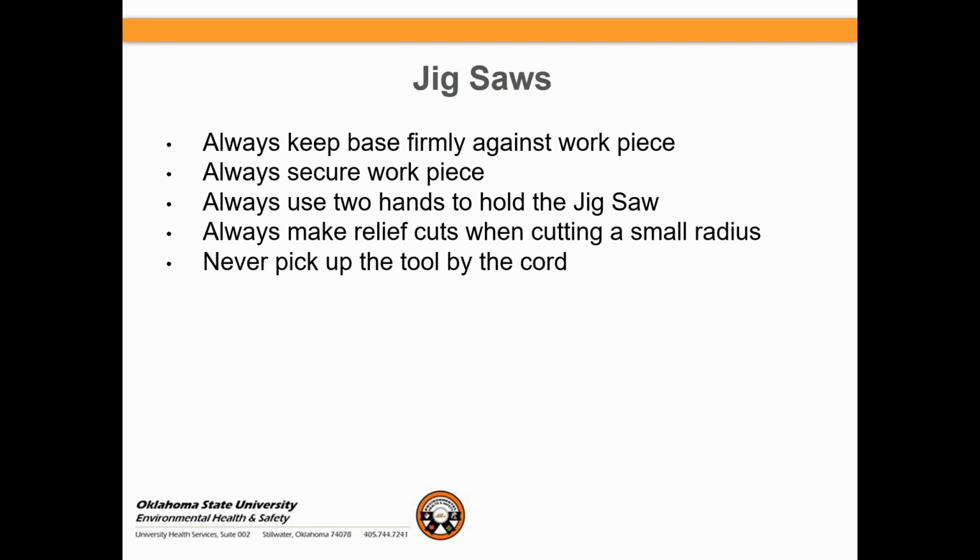Basic safety information on these includes: always keep the base firmly against the work piece, always secure the work piece, always use two hands to hold the jigsaw, and always make relief cuts when cutting a small radius. And one other thing too: never pick up the tool by the cord. Always use the handle to pick up the tool.